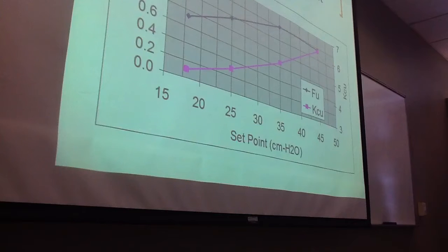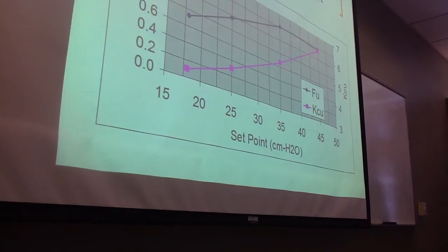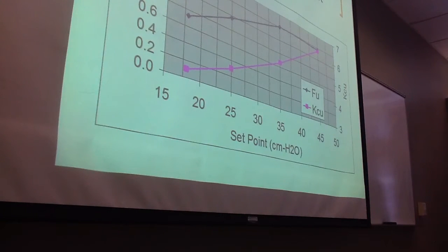Now, on the relay feedback, you had options to adjust the set point and the floor and the ceiling. In the experiments, I was asked to go through and figure out what happens when you change the set point. So what I did was I kept the floor and the ceiling at the same spot, which was the floor at 20% input, and the ceiling at 80% input. And I just moved the set point.